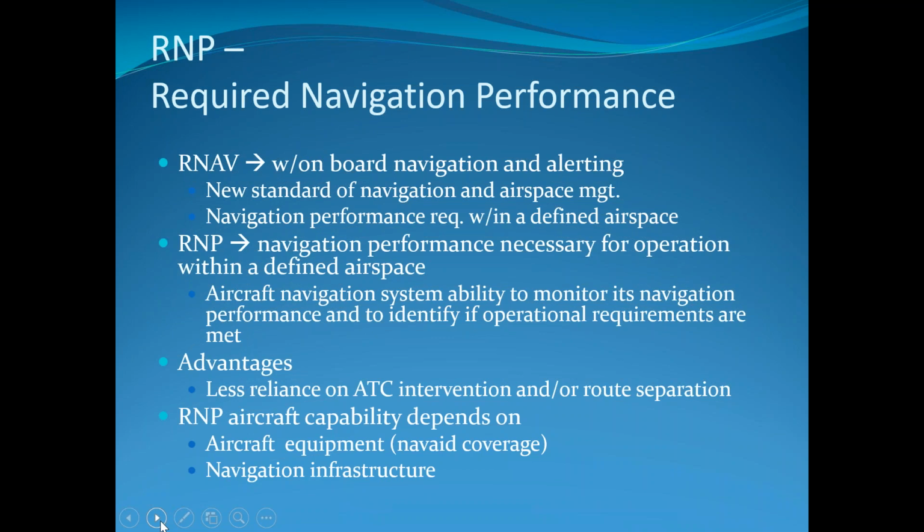All this is really saying is that in order to be able to use it, the preciseness of the satellite coverage or navigation has to be precise to within a certain amount of nautical miles. Like, it usually has to be precise to within 1/10 of a mile, or within 1/2 of a mile. There are different RNP levels that they use depending on the type of approach.